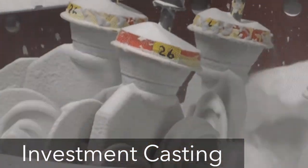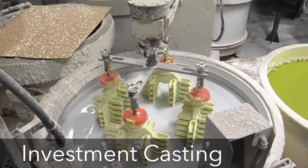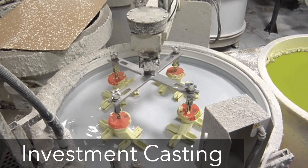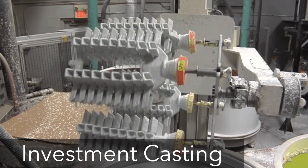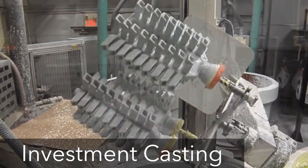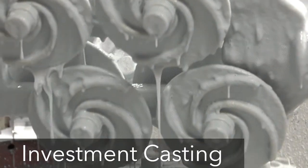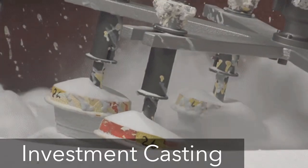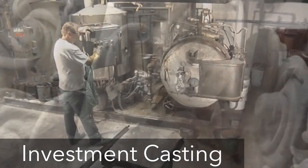The pattern is then dipped into a slurry of refractory material such as very fine silica and binders, including water, ethyl silicates, and acids. After this initial coating has dried, the pattern is coated repeatedly to increase the thickness for better strength. The term investment derives from the fact that the pattern is invested, or surrounded, with the refractory material.